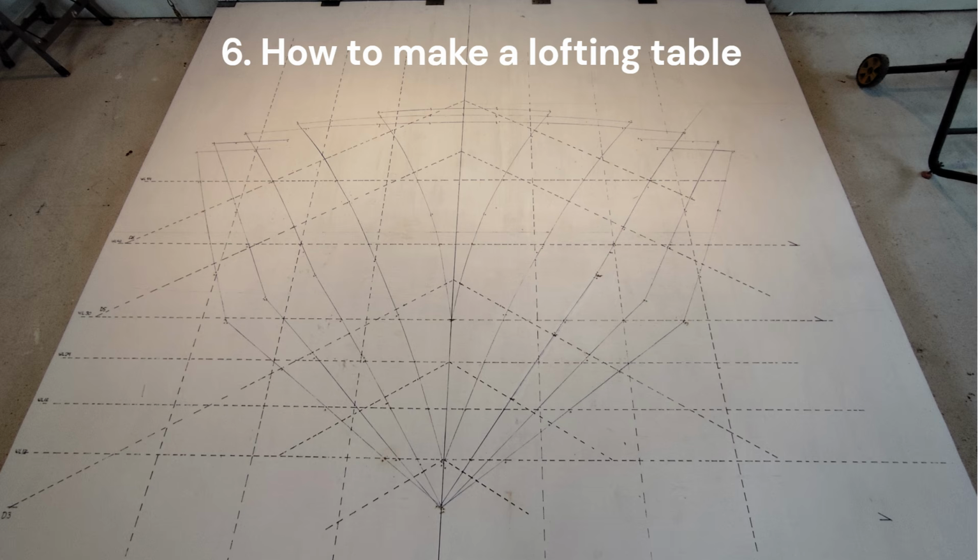However, most private builders don't have that space, so they instead build a lofting table big enough for the stations in their build. Whether you do full-size lofting of the whole boat, or just stations and other parts, you must have some sort of wire, beam or laser representing the middle of the boat in your build.